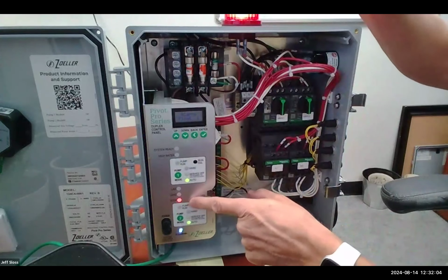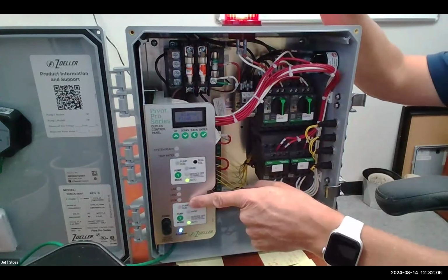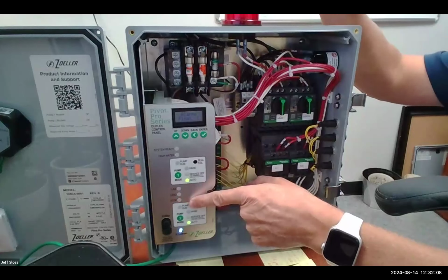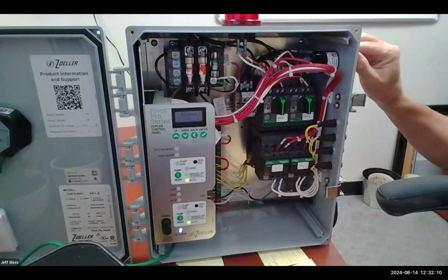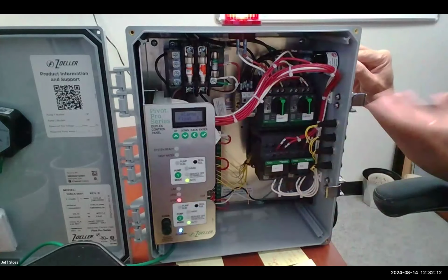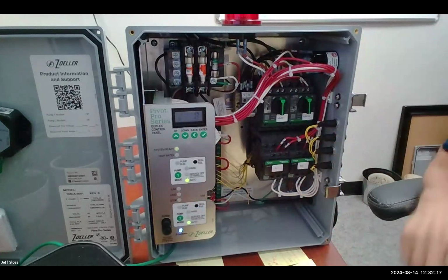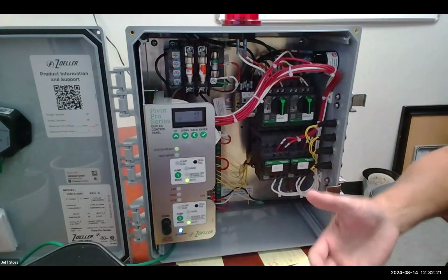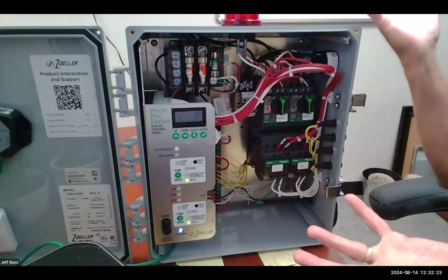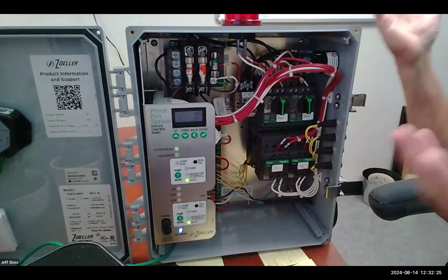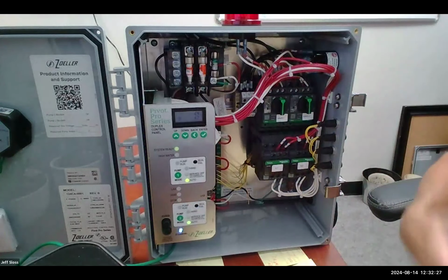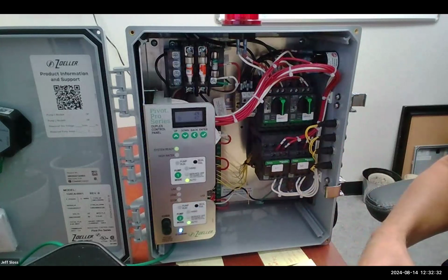Now you notice the alarm is latching, staying in place. We're going to clear that out. It stays in place until somebody comes and does this, which is I'm holding the silence toggle down and clearing that out. The reason that's important is so often somebody's called out to a site and they get there and there's no evidence of what was wrong. They have no way of diagnosing it. So we're giving people that extra information to be able to diagnose a problem.